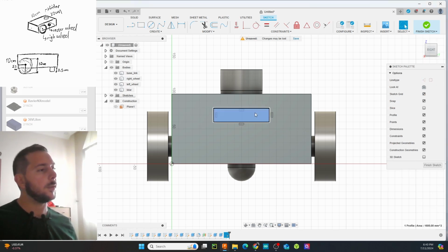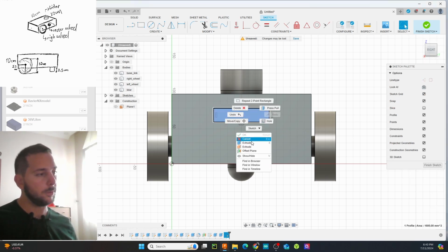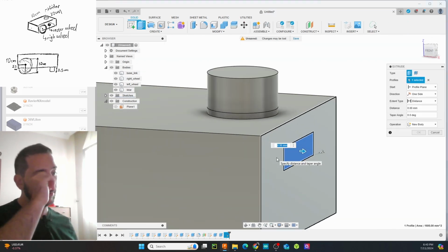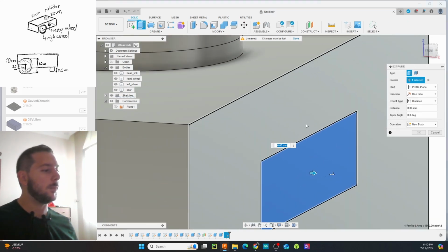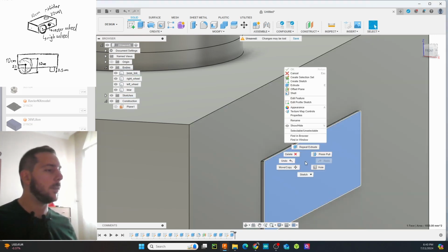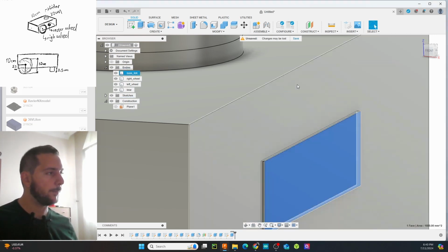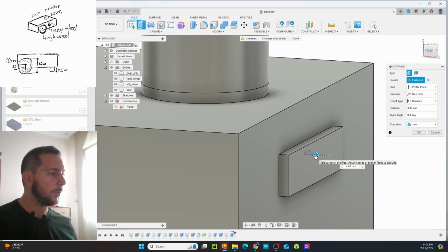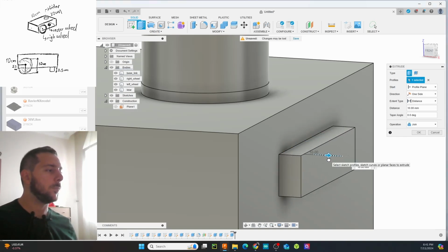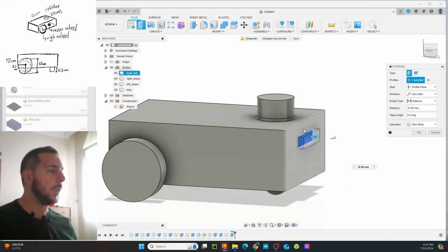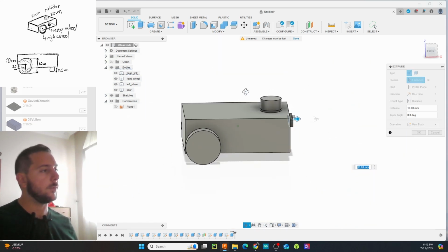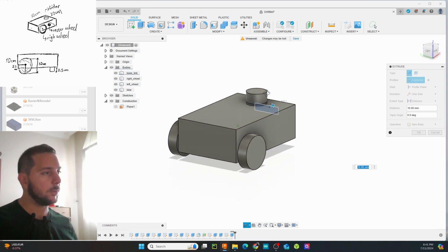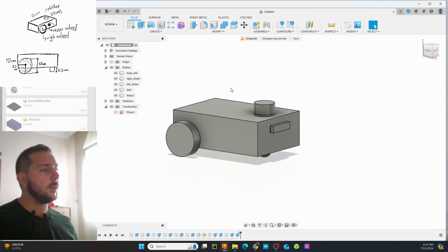And this is the camera holder. As I mentioned with the LiDAR, we first have to add the holder. So I'm adding a 1 millimeter holder in here, then I'm adding the real camera. It's going to be 10 millimeters or something, so it's going to be a new body. By doing that, we're concluding our robot. Okay, that's nice. So you can see this is our robot.